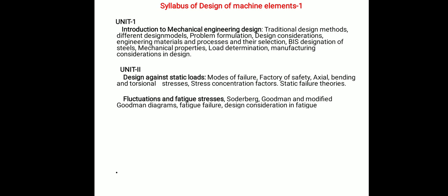Whereas in case of a fluctuating load, whenever the component is subjected to a fluctuating load, we can analyze the component closer to the real-time applications. Okay, if you see any mechanical component under service conditions, it is subjected to a fatigue loading condition rather than a simple static loading.